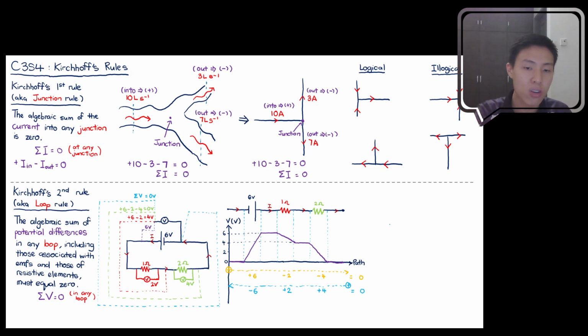So what I am trying to prove here is you can choose to analyze the loop in any direction you prefer. You can analyze it in a clockwise direction, not following the direction of current, or in the anti-clockwise direction, following the direction of current. If you are opposing the direction of current, passing through a resistor will behave the opposite way of what we usually know: usually it's a loss, but opposite it will be a gain.